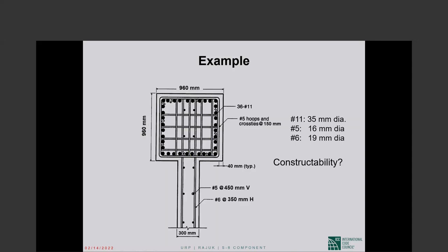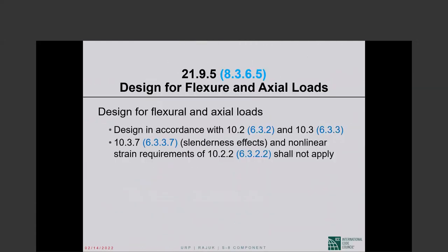Now you tell me, first of all, placing the reinforcement is difficult. Having placed the reinforcement, concrete placement is not easy. And then, as I pointed out, there is the shear failure aspect of it. We are building flexurally overstrong shear walls, which will almost certainly fail in shear before they can fail in flexure in an earthquake.